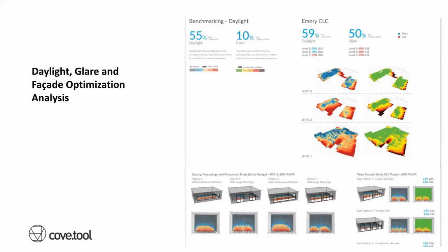The shoebox model is actually developed by aggregating the different elements of your building. So it'll take all of the faces that face north and produce a 30% window and wall ratio as a base. And that allows you to test that and see how that works. One issue with this is it doesn't necessarily account for self-shading of the model or other context shading in the shoebox model, as they generally don't. But as they're pulling your window to wall ratio, it might become a more apparent issue than if you're doing a proper shoebox model that you would do in other programs.